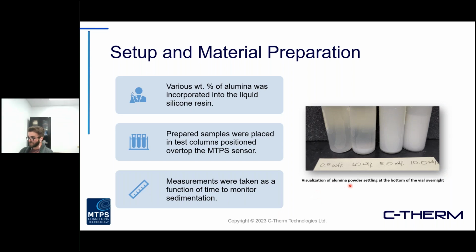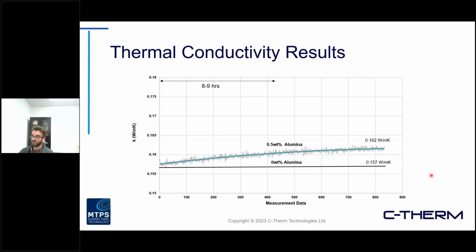This is kind of a visualization of that alumina powder that had settled towards the bottom of those tubes overnight. So again, this sample here wouldn't necessarily be exactly representative of these larger feedstock materials, because there are stability agents that are introduced, thixotropic agents as well, that help with some of that stabilization. But again, really you're fighting time, and at a certain point, these sedimentation and agglomeration issues will effectively take over.